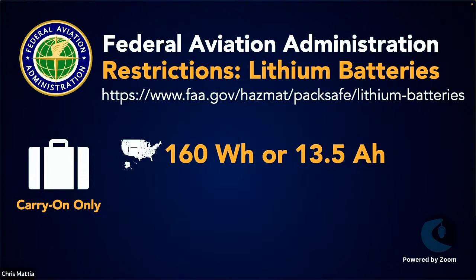Another one of the key restrictions is the size of the battery that you're allowed to travel with. If you're traveling in the continental US, you are limited for commercial airlines to 160 watt hours, or if you do the math, roughly 13 and a half amp hours. Most battery manufacturers don't sell a 13 and a half amp hour battery. They usually sell a 12 amp hour, and then smaller or quite a bit larger. So you want to make sure you're within that restricted area. Something less than 13 and a half amp hours is more than likely going to be a 12 amp hour or less that you can bring onto the plane with you.